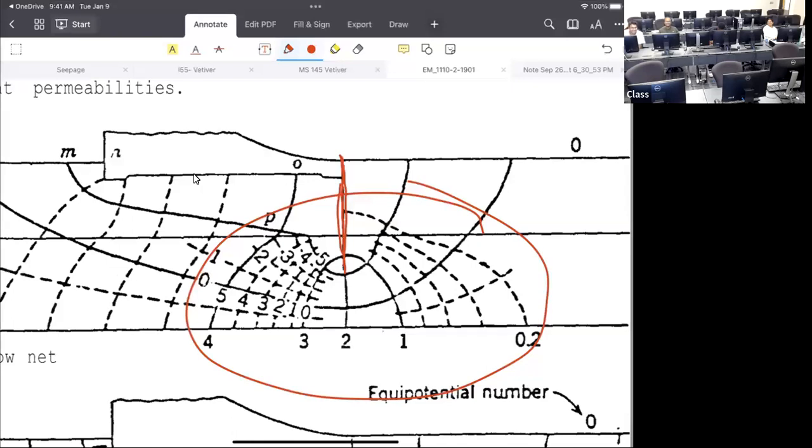That's it. The sheet pile will do nothing. It just forces the water to travel longer. As the water travels through the soil, it dissipates the energy. The soil does everything. You're just forcing the water to pass through and changing the direction.